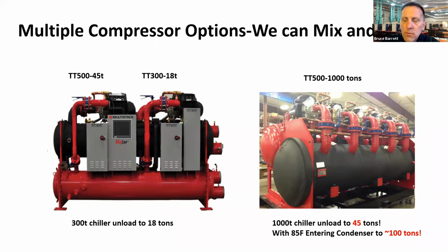Yeah, so running condenser water through till it warms up and you can have enough temperature differential to start compressors and do mechanical cooling. I have heard about that. Usually when it runs through your condenser, you can't recover heat fast enough. So a three-way tower bypass is usually bypassing the condenser itself, but you can run water right through it.